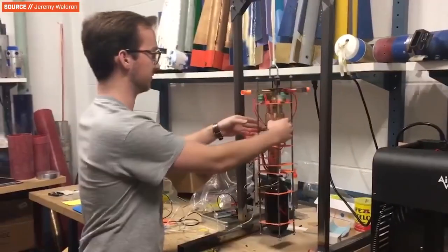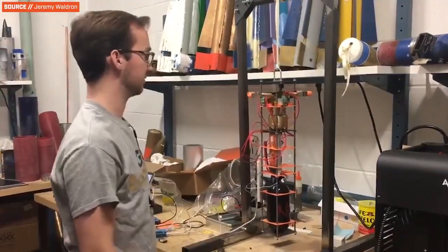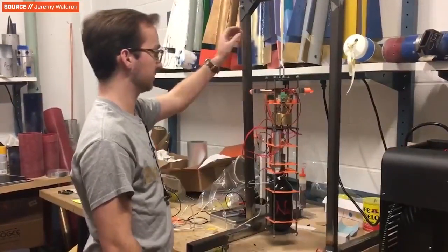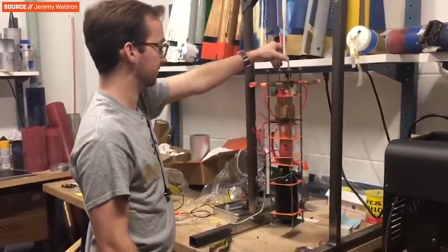So again, that's actually another huge limitation of cold gas thrusters, is just in the overall enthalpy, or really the lack of heat in the system, which prevents them from really being that efficient. However, they're very simple and extremely reliable and really only have one moving part, a simple valve. That's about it. And despite their low efficiency, because of their simplicity and lack of parts and weight, sometimes they're actually the best choice for really small spacecraft like smallsats or CubeSats.